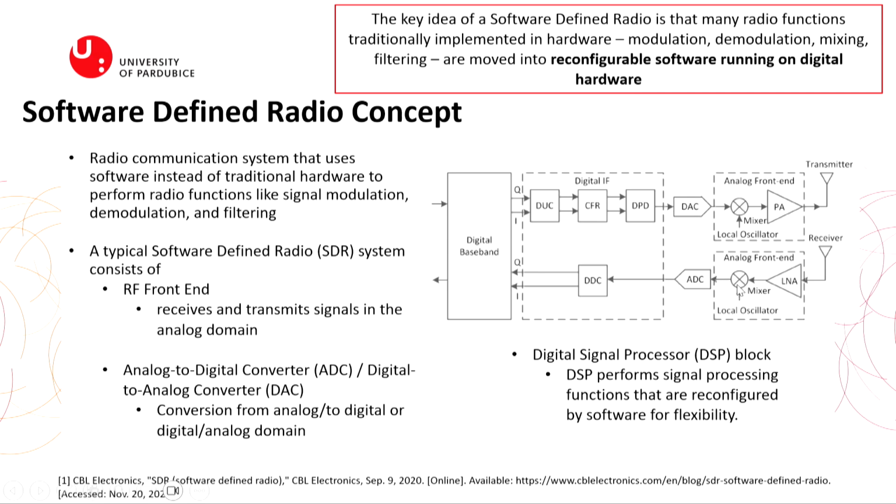Then there is a mixer, which converts to some lower frequency. And then there is the ADC converter, or the opposite, the DAC converter. So you can see only this part is analog: only amplification and a mixer for conversion to lower frequency. And then there are just converters, and from this point it is all digital.